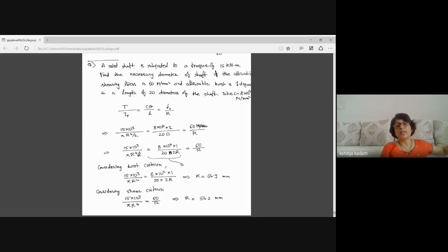उन्होंने बोला है कि ज्यादा से ज्यादा shear stress 60 न्यूटन पर mm स्क्वायर हो सकता है, तो 60 अपॉन r. सो दो कंडीशन दिए हैं, मैक्सिमम shear कितना हो सकता है और मैक्सिमम ट्विस्ट कितना हो सकता है. And our aim is to find out r. So first we will consider twist criteria. We will take these first two parts of the equation. We will equate it and we will find out the value of r. And considering shear criteria, I will take first and the last part of the equation.